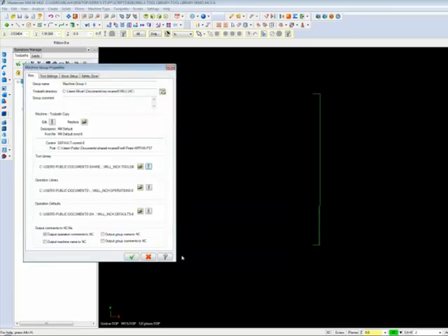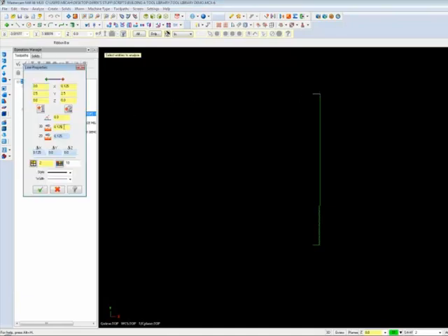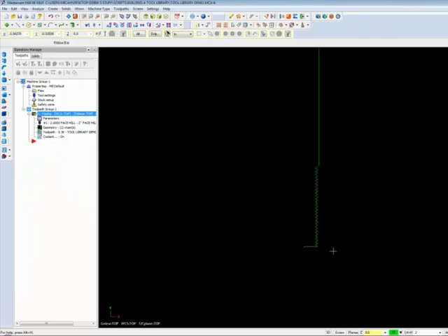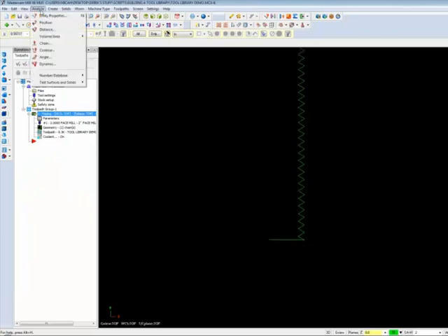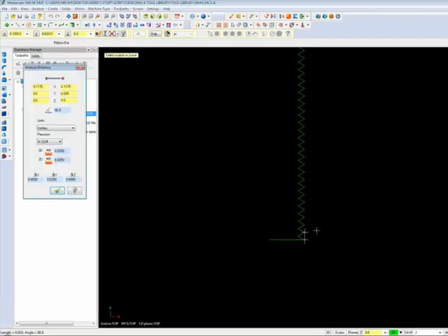Sure. Yes, I did actually. So if we exit out of this, we can use the analyze function, and this line here, which represents half the shank diameter, is 1/8 of an inch long. And if we go in here and we do an analyze distance, these threads, 40 threads per inch is 25 thousandths per thread. So from the end of one thread to the end of the next is 25 thousandths there.